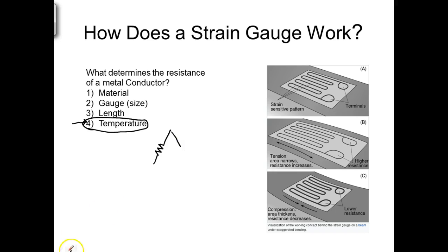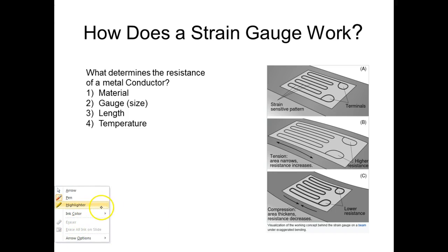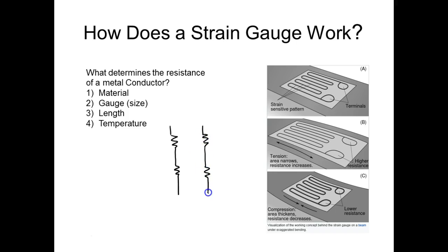So since it changes the resistance, what we would do is come over here and put this in a Wheatstone bridge. I'm not going to draw it as a bridge, guys. I'm going to draw it like a series parallel circuit. So we always use these things in pairs. Or we should use them in pairs.